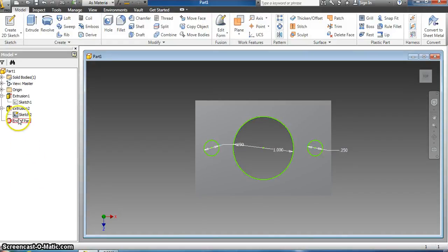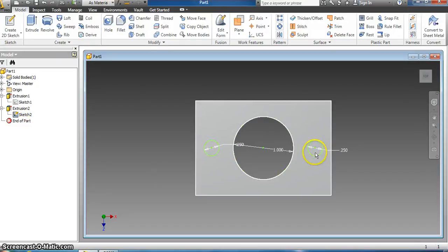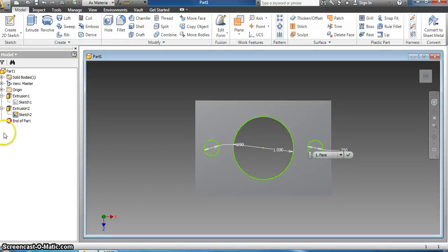So I'm just going to right click on that. You can see that it's not grayed out anymore. Sketch 2 is colored, and it shows me those exact areas where I have those 1/4 inch circles that I drew earlier. So again, if something you know is drawn disappears on you, it's probably because the visibility is off on that particular sketch.